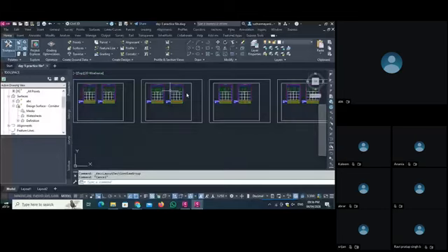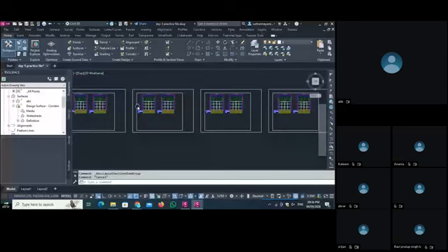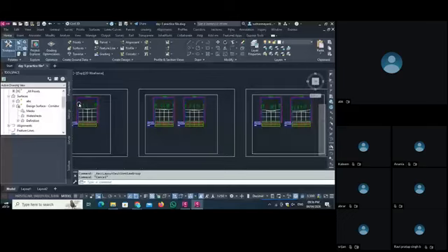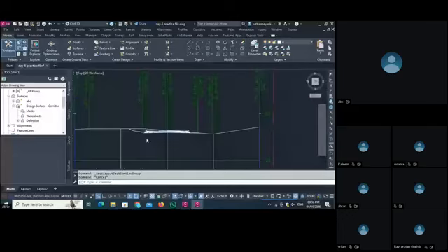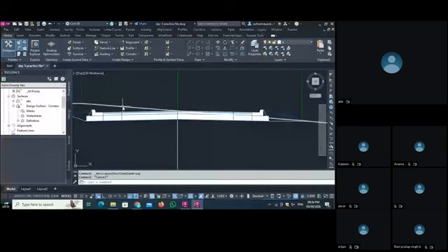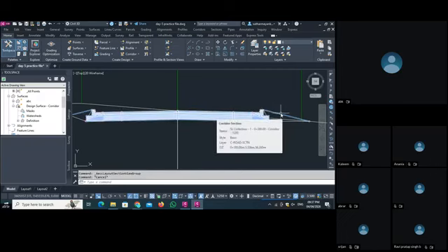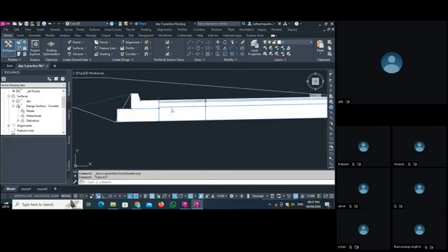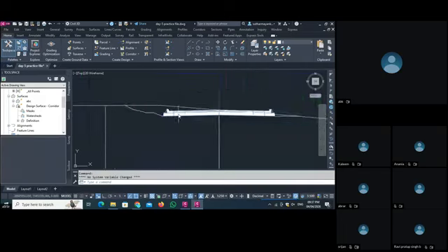Because our starting chainage is on a flat terrain, we go here to the chainage of 280. Now you can see all the things here. This line, I select the first one. Second, you see the top profile on the corridor surface, and third your alignment.